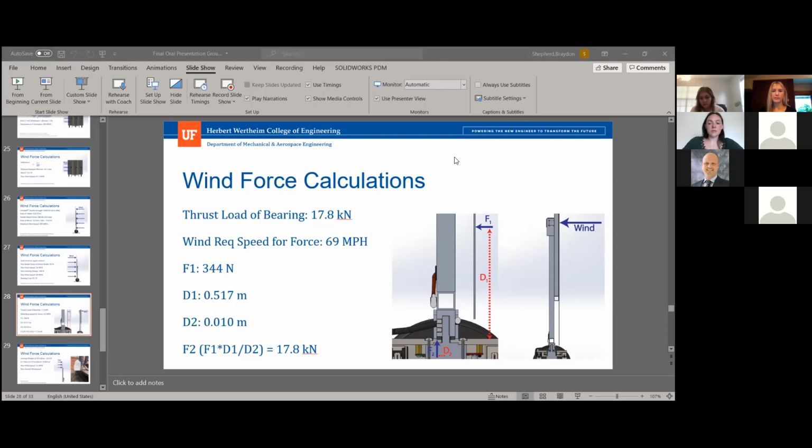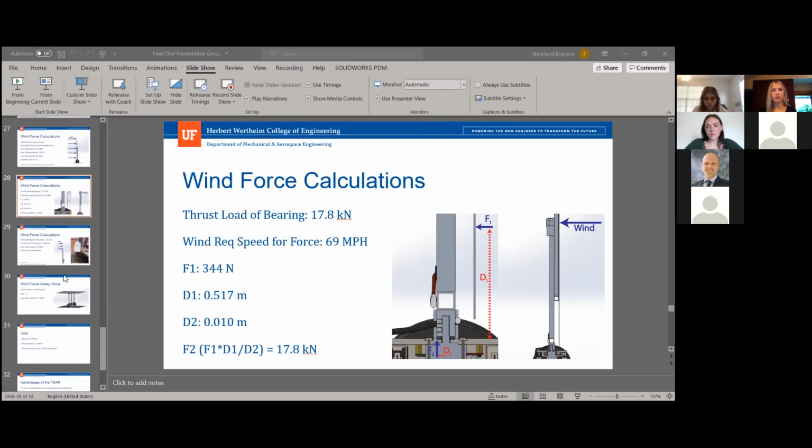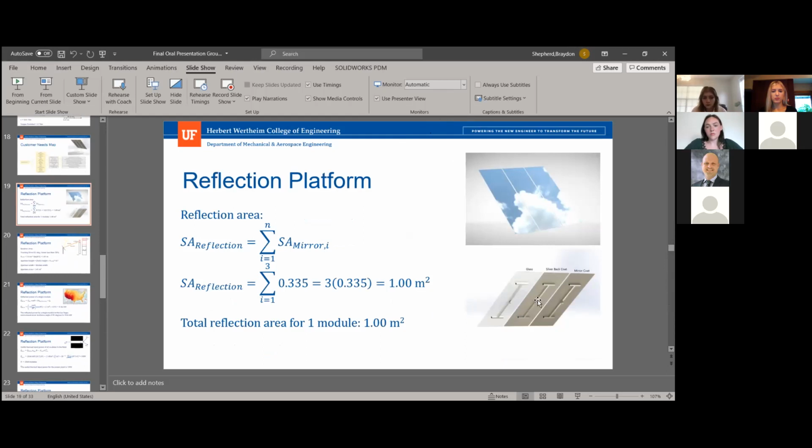I have one really quick question, tangentially related to this. For assembly or manufacturing, are there any locating features on the mirror to ensure that you install them perfectly symmetrical about all these axes? I'm talking about actually using JB Weld to get these mirrors onto the axes. Is there anything to ensure that the assembler does that properly, seeing that it seems pretty important that all these mirrors are exactly symmetrical about both axes?